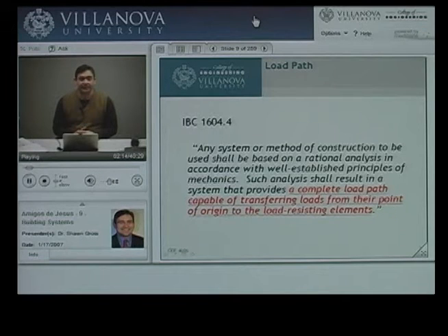So we're basically looking at different types of loads, of course, starting at different locations. If I consider a generic building, say here, in the United States, sitting here in the Shear building, for example, if I take a snow load on the roof, the question is, how does that snow load get transferred from the roof eventually down to the ground? If I take a live load or a dead load in a classroom, how does that load get transferred? Does it need to go through beams or columns or walls? What exactly is our mechanism? So that's what we're going to look at.